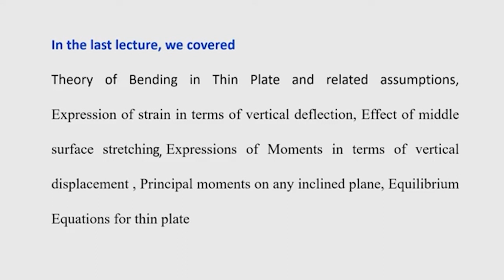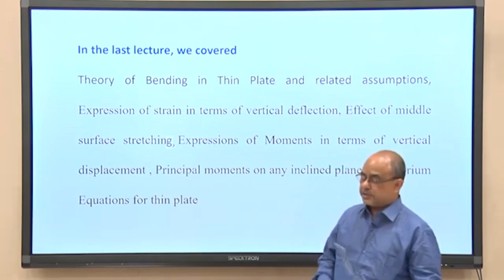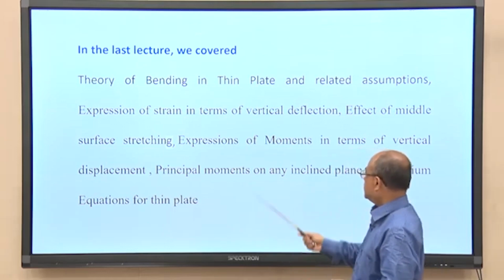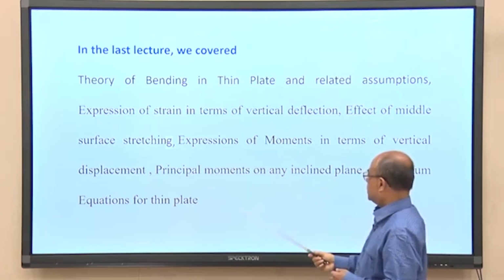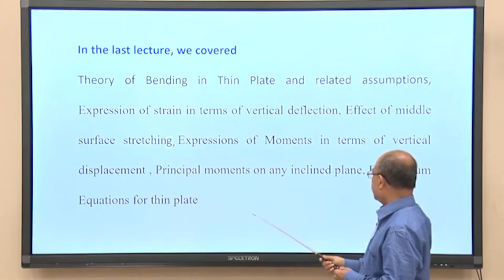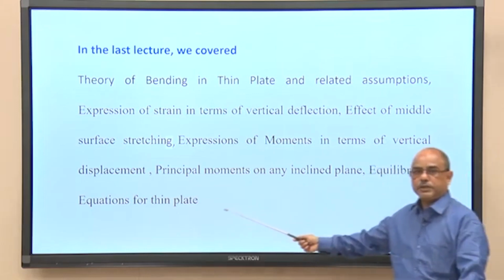So, in the last lecture you have learned the theory of bending in thin plates and what are the assumptions related to bending, expression of strain in terms of vertical displacement we have obtained, then effect of multiple middle surface stretching that we have obtained, expression of moments in terms of vertical displacement, principal moments on any inclined plane, equilibrium equations for thin plate.